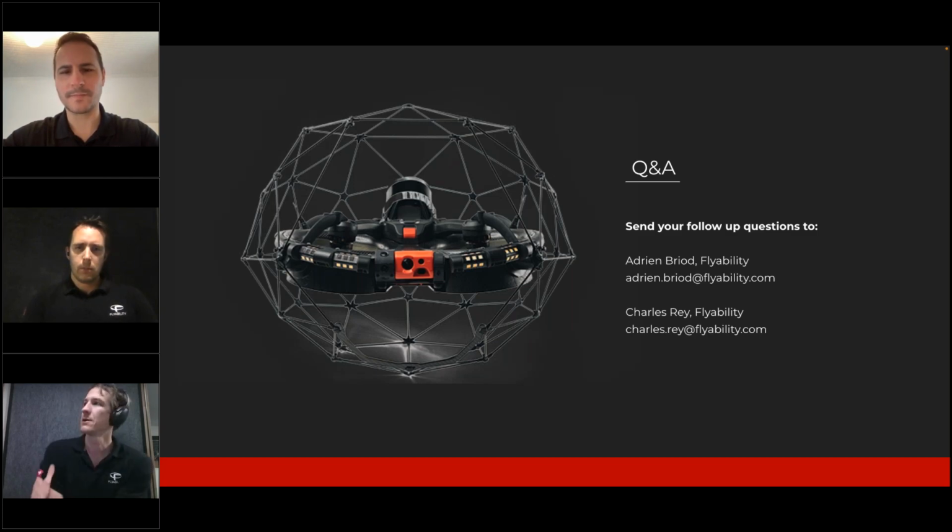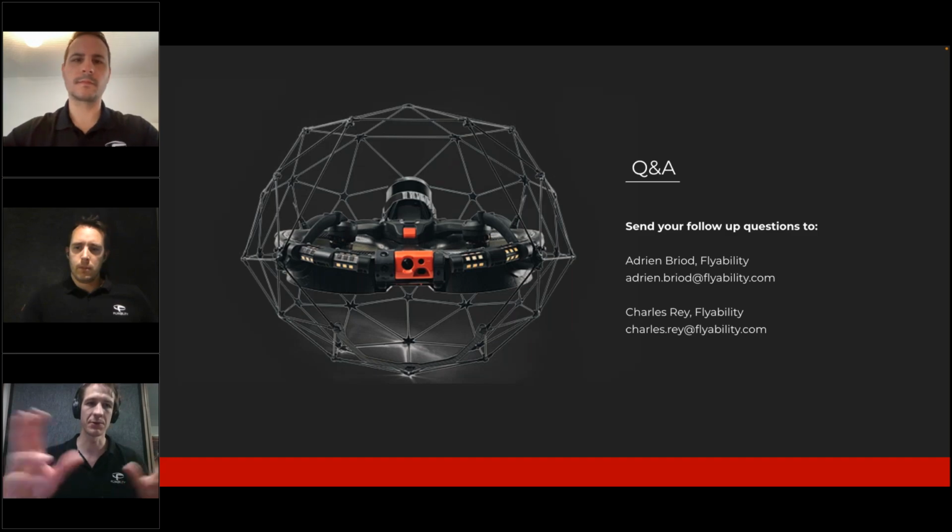Yeah, so I would say one way to georeference your model is to match it with another model you may have that is georeferenced, or sometimes you just don't need any georeferencing, but just to merge models. That's actually what we did for one part of our test, where we took the takeoff area and matched it with ICP to the ground truth.